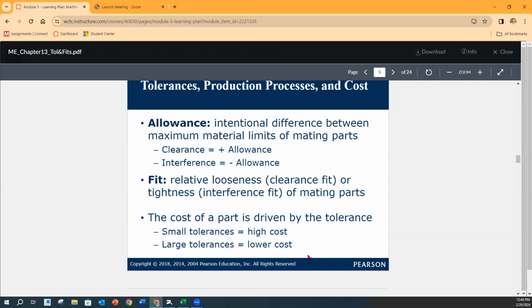You as the designer have direct control over this. For each and every dimension that you put on a drawing, you want to think about whether the tolerance I have on here is appropriate, number one, for fit and function, but number two, for manufacturability. Is it that critical that I'm only going to be able to make it on this, that, or the other machine? Or on the other side of it, if you put a 3-place decimal on something and it defaults to the title block and it's plus or minus 5 thousandths, and it's maybe the length of a cover, does it need to be within 10 thousandths? Could you do it maybe plus or minus 20 thousandths to make it 2 decimal places?